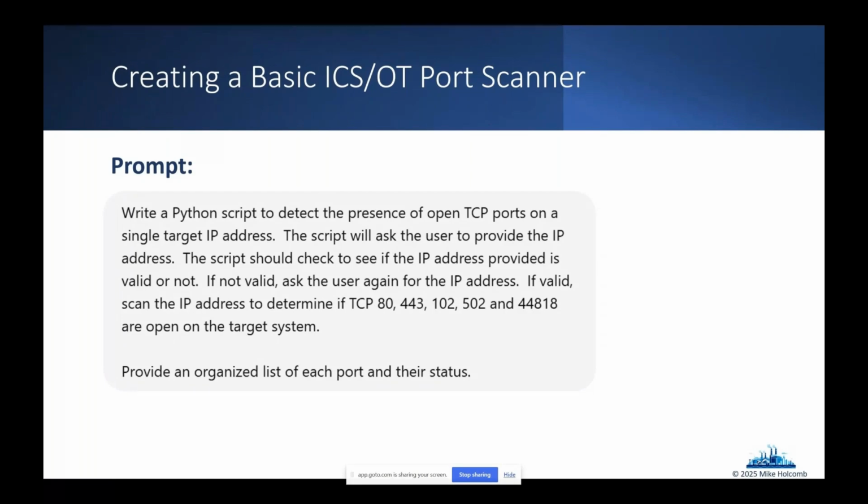And then we see some OT protocols like S7, which runs on TCP 102, Modbus, which runs on 502. We're going to talk a lot more about Modbus later. And EtherNet/IP, which is 44818, so it's like Rockwell devices. And S7 is for Siemens, and Modbus we see on pretty much just about everything because it's open source and it's not associated with a particular vendor.